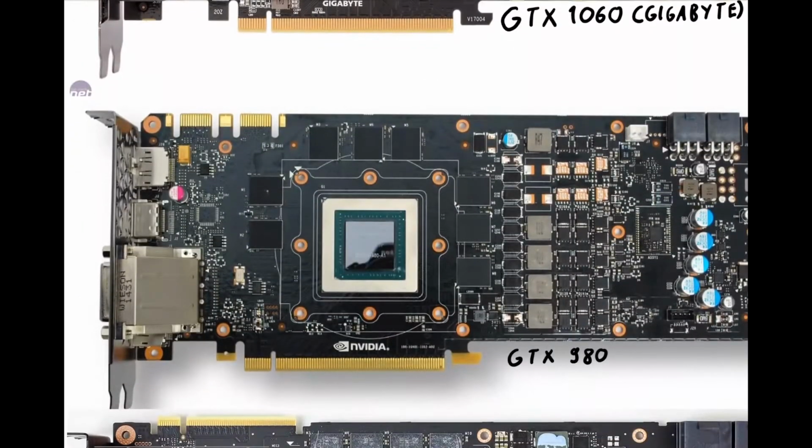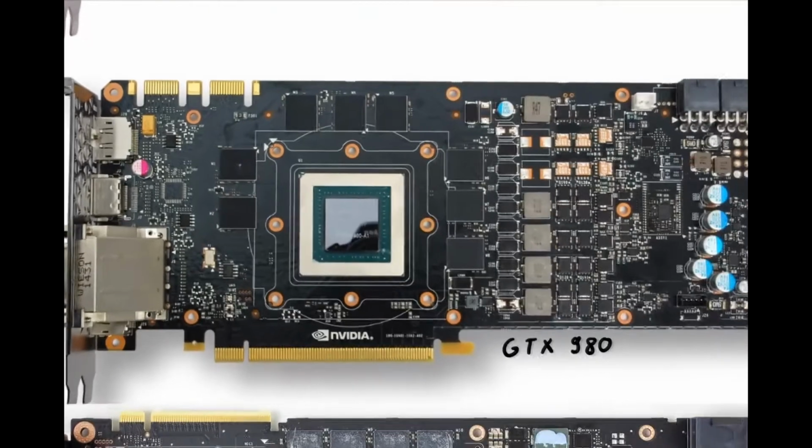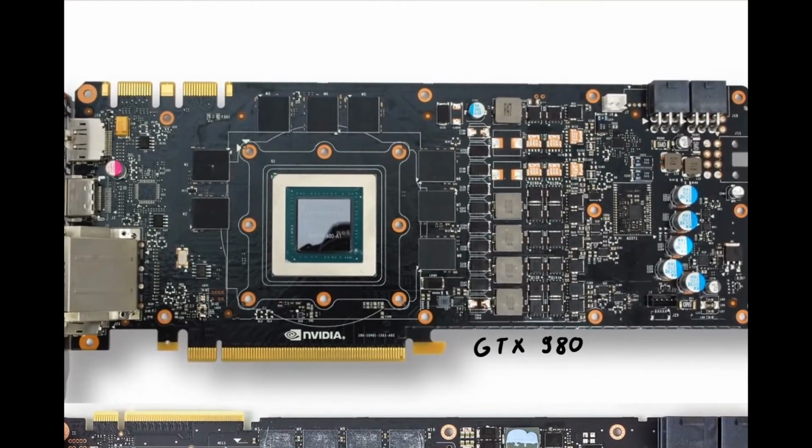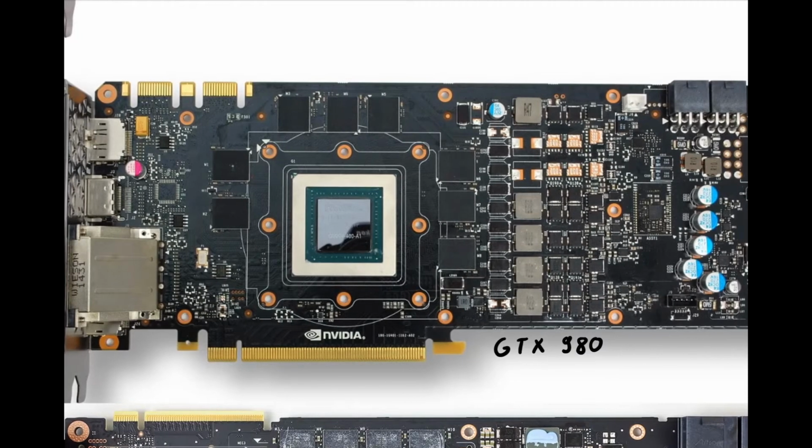So then over here our GTX 980. We already see from the size of the GPU, the amount of power connectors, and the amount of memory chips that this is a more powerful card, and the VRM reflects that. Let's get VMem out of the way. It's a 1 phase again with discrete MOSFETs, pretty unexciting. And then VCore over here, which is again the special version that is actually 6 phases, but with four inductors.